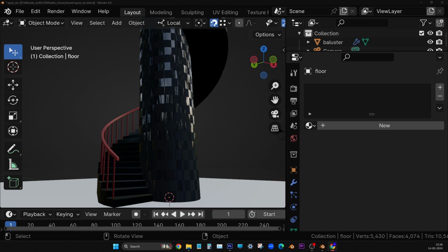Select any one vertex. Now press function dot. Now you zoom it. Yeah, this is how we have to do, because in Blender, beyond one point, the camera won't zoom. We have to make a second effort to get there. Right. Now go to edge mode. Now Alt A, because you would have selected something already. Have a fresh deselect first. Alt A.